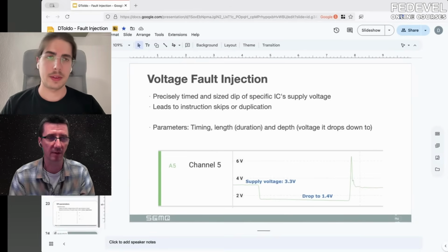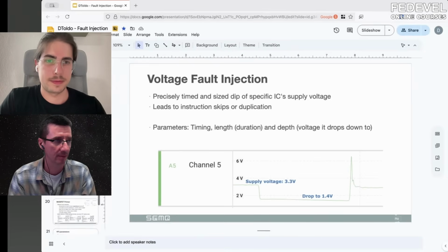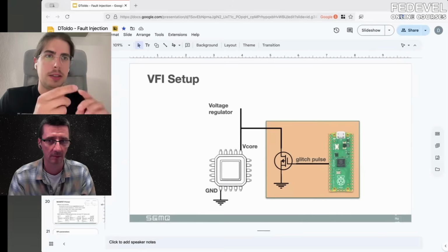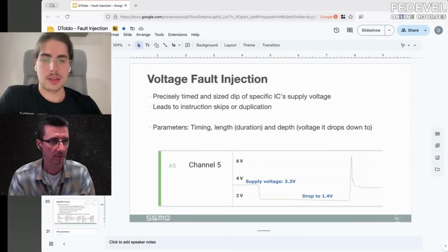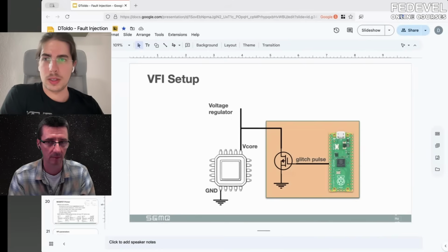I was actually thinking about this when you were talking about this. Other attacks that work on voltage use two power supplies and they switch between them. The first one is regular 3.3 volts, and the second one is like 1.4 volts. The challenge with that is that you need access to the V-core and you need to cut it, so it's more invasive. Our attack here, we could actually just use a decoupling capacitor that's sitting here on top, and we can just solder a wire to it and perform this attack, remove it, and nobody's seen it.